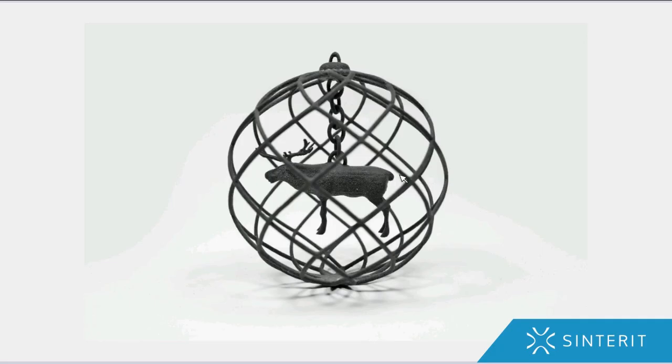You see, having support structures can have an impact on what you can or cannot print. SLS technology allows you to print even the most complicated models in just one piece. The efficiency when it comes to both costs and time should be obvious, not to mention the freedom of form it gives you, especially when it comes to building complicated prototypes. Some of them can be quite expensive when making them with conventional methods like machining or molding or casting. Some of them will be impossible to make otherwise than using additive manufacturing processes.